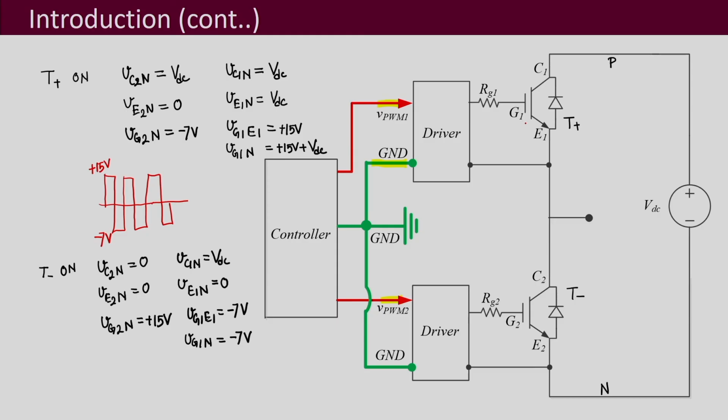So the driver should be capable enough to give that much voltage, and there may also be a driving current requirement, whatever this gate requirement Ig is, which should be sufficient to drive this gate emitter region. It should be able to provide the charge Qg that is required to turn on the gate emitter region, and also sink that much current when we are turning it off. That is also something the driver does, and is why we need it.